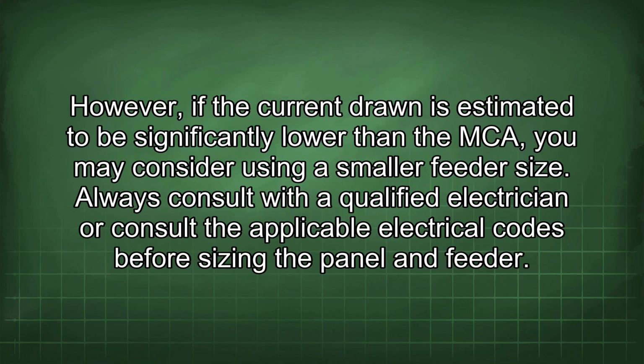However, if the current drawn is estimated to be significantly lower than the MCA, you may consider using a smaller feeder size. Always consult with a qualified electrician or consult the applicable electrical codes before sizing the panel and feeder.